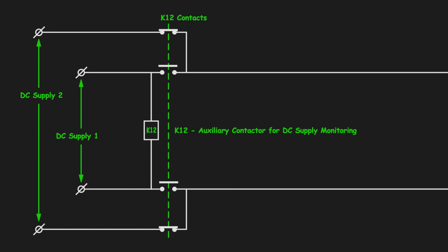Some manufacturers provide fuses in the positive supply line of both supplies and links in the negative supply line of both supplies to provide better protection for the DC supplies. But some manufacturers do not recommend providing any fuse at the entry point of the circuit breaker supplies, because if any of these fuses blow, it may cause an interruption of the DC supply. So there is no need to provide them, since DC fuses are already provided at the supply point from where the supplies come to the circuit breaker. So, an additional fuse and link unit may not be required here. Another difficulty is that providing a fuse here means introducing more chances of fuse blowing.